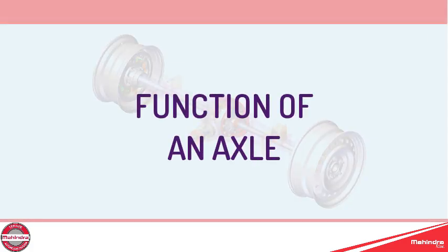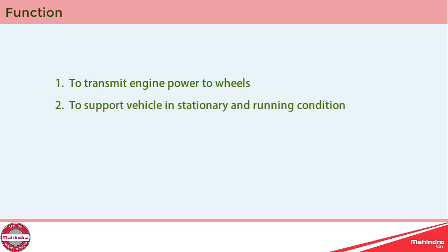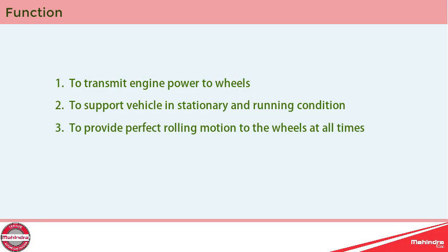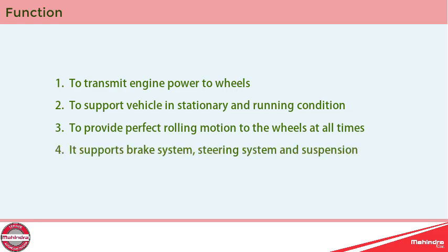Function of an axle. To transmit engine power to wheels. To support vehicle in stationary and running condition. To provide perfect rolling motion to the wheels at all times. It supports brake system, steering system and suspension.